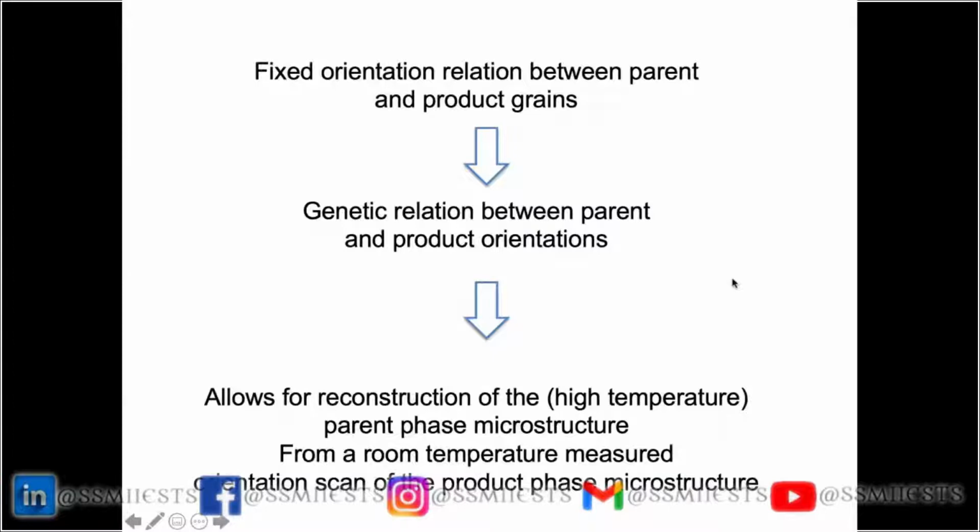That is that the overall majority of our experimental observations are done at room temperature, whereas a major part of the processing occurs at very elevated temperature. So you always have to think back. Typically you quench from the austenite phase, then austenite turns into martensite, and then you say, where I see my martensite in my microscope, there it was austenite before at high temperature.